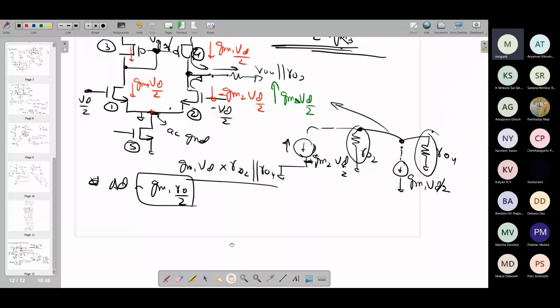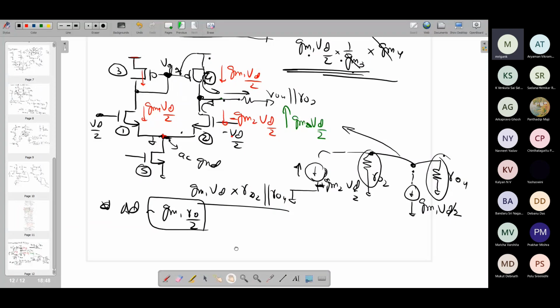Now this is okay. Again, we have done some approximations. That approximation basically includes ignoring the RO of RO3, RO4 while calculating the small signal current. So when we just transferred the VG, we are ignoring basically the RO3 contribution, but it is not going to be very significant. So it is still okay. This is a simple analysis which is valid.